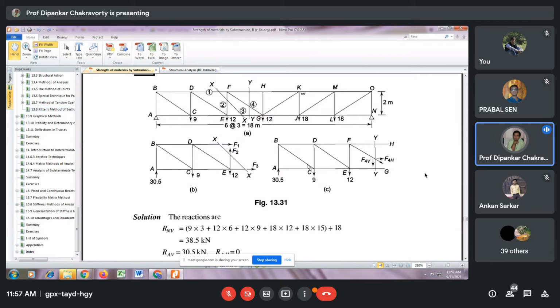I will give you another example. If you have a beam where both the supports are roller supports, and it is subjected to only vertical force, can equilibrium be established? You tell me. Both the supports are roller supports, which can provide vertical reactions. Horizontal reaction will not be there. I understand, but if you have vertical load only and rollers which can give vertical reactions, is equilibrium possible or not? Yes, sir, it is possible.